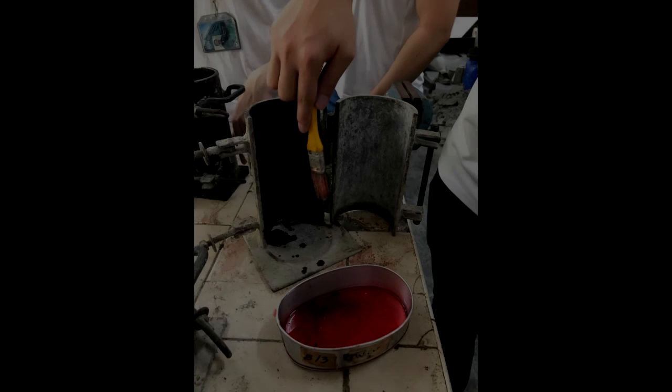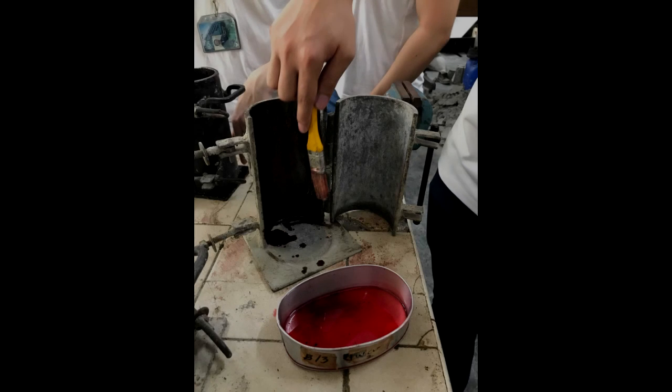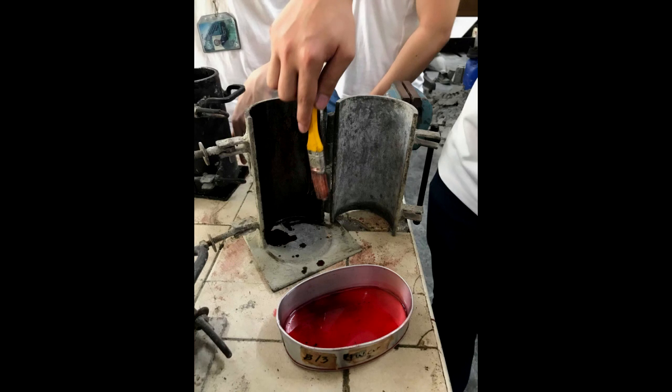It is important to consider that the containers or molds must first be cleaned to be free from impurities and voids. The interior of the molds must be lubricated with oil prior to the pouring of the concrete mix to prevent the sticking of concrete on the surface of the mold. Then, the concrete must be poured evenly and constantly tamped to distribute the concrete and get rid of as many voids as possible. After this process, the concrete mixtures were then placed aside for 24 hours to harden. After that, the concrete specimens were taken for curing.